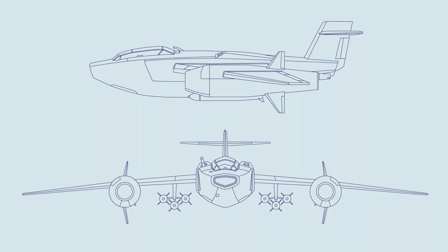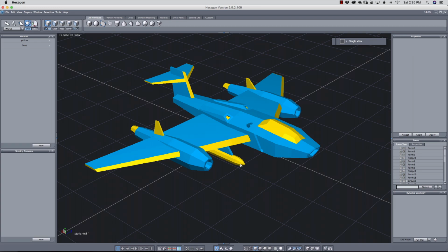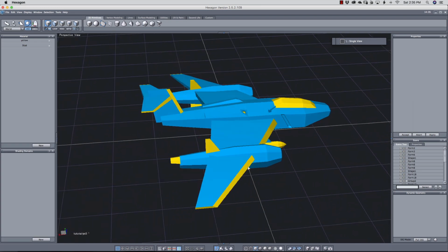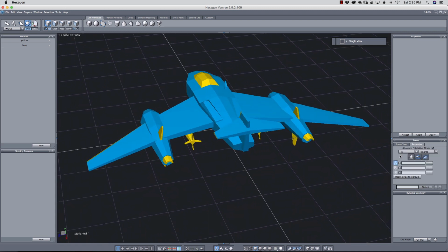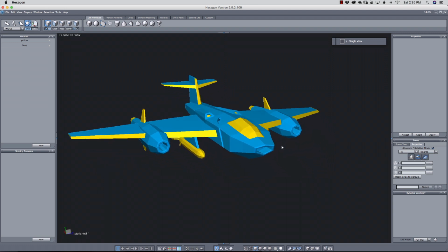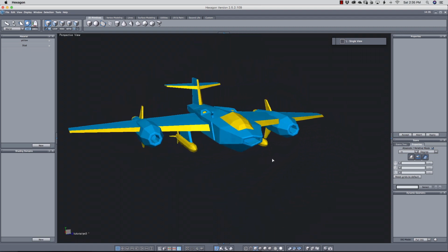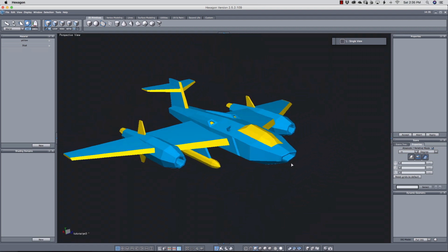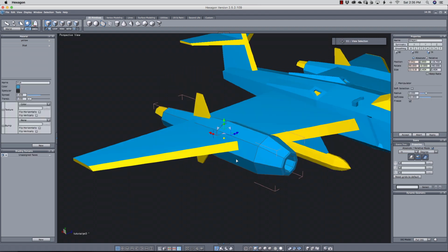Okay, so that was a lot to go over. To speed things up, what I did was complete the model, and that's what you see here. Now, I was going to end the video here, but after I finished my jet design, I found there were a few more things that I should go over. The additional tools to quickly cover are adding a cylinder object, quick extrude, bevel, duplicating objects, mirror, filling holes and capping them, the scene tree and grouping, and then I'll show how I colored the jet. So let's go over that part by part.